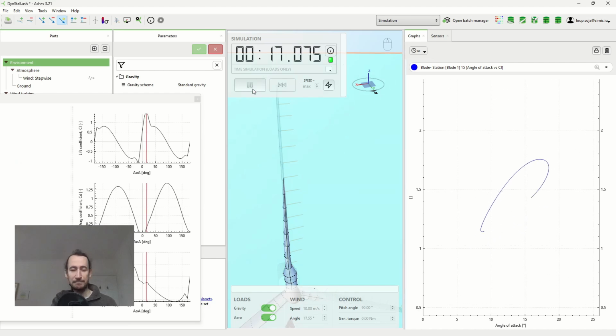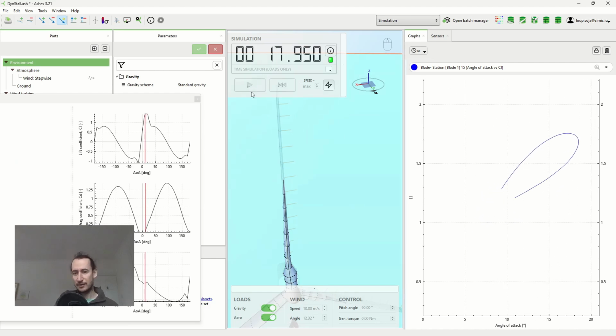And well, my understanding is that this is because stall occurs when there's flow separation, right? When the flow is not attached to the airfoil anymore. But what happens is that the location of the separation point has a bit of delay. If you increase the angle of attack, it remains at the place where it is, and then it moves along the airfoil. But there's a little delay in how that happens, and that's why there's this dynamic stall phenomenon.